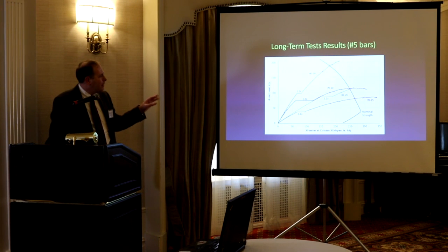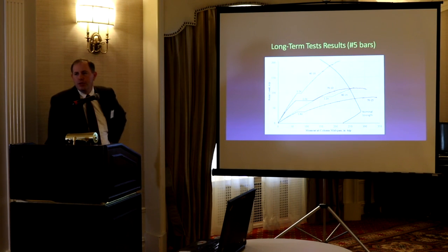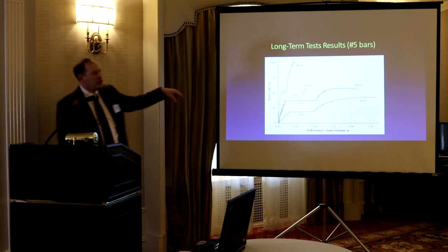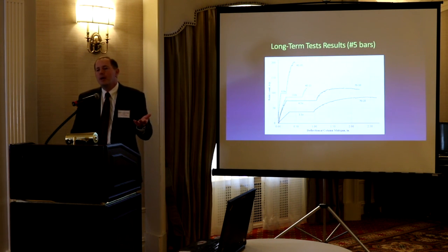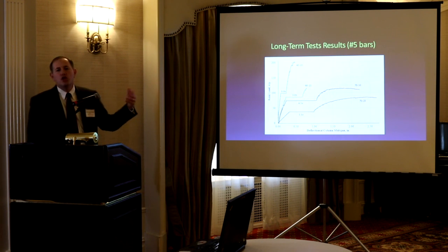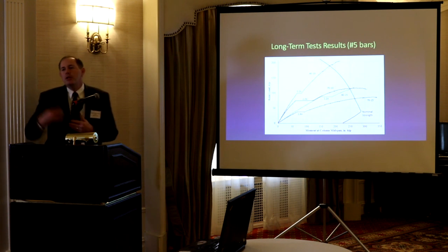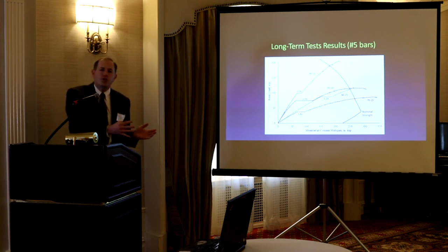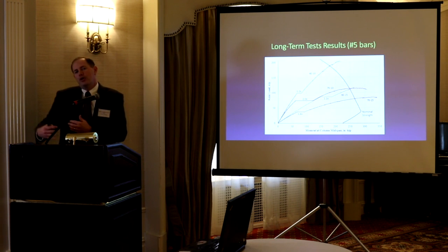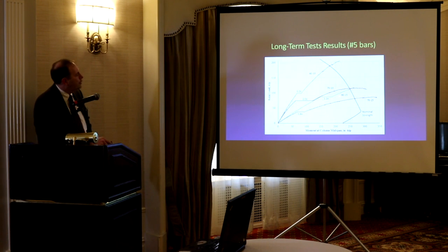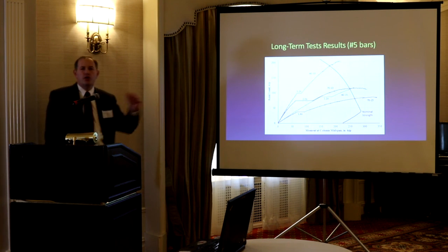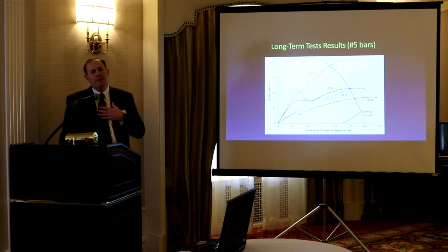So we take that, we can convert that to moment, so you can put in a plot that you're used to seeing. Interestingly enough, the deflections look much higher, but when you convert to moment, it turns out that the jumps are not as significant. They're 1.2, and then it's 2 and 1.4. And so you'll see the moment change is not as large, because you have a first order deflection, and just look at the second order change, okay? So you'll see again, they all fail, even after sustained load, beyond the nominal strength, which is great. I mean, that's what we want to see.